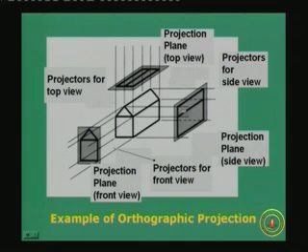Okay. So, top view is the top, side is on the side, and the front is to the left of you. So, there are three planes, and as you can see here, the projectors for the top view, front view and side view respectively are all parallel. If you take a group of rays for the side view only, or only for the top view or for the front view, they are parallel to each other and they come out of the object and intersect the plane and they keep moving towards infinity. They are all parallel to each other, they will never intersect.